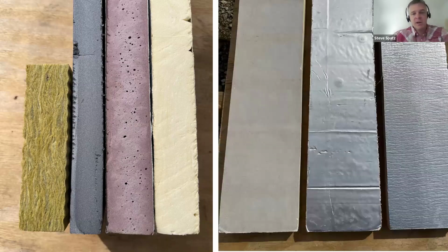So depending on which of these types of material you would use as an exterior board insulation is going to affect the characteristics of that assembly's drying potential, whether it can dry freely to the outside, and that would impact the choice of the WRB in place. Or if, because of that rigid exterior insulation choice and/or the facing or backing on it, the potential of vapor flow through that material to the exterior is limited, retarded, or stopped, you're going to need to define other components in the assembly that will allow drying to the interior.